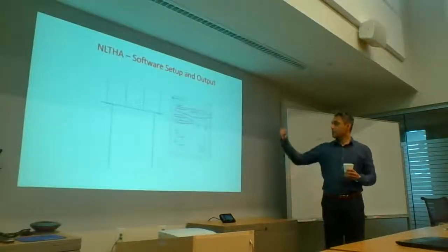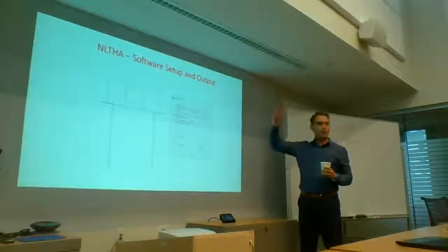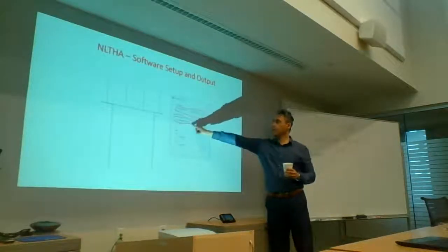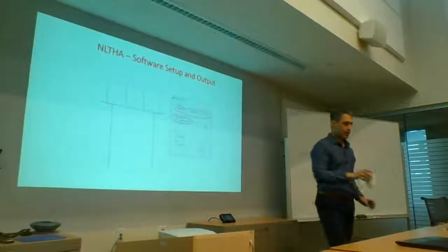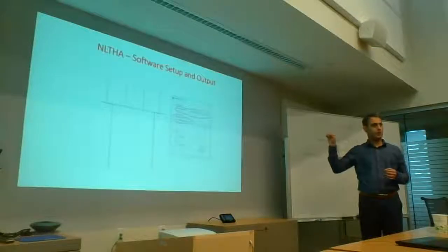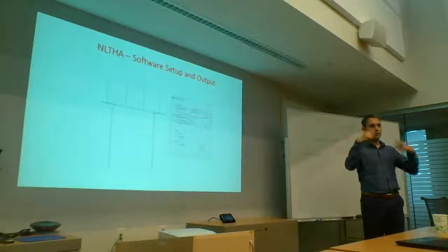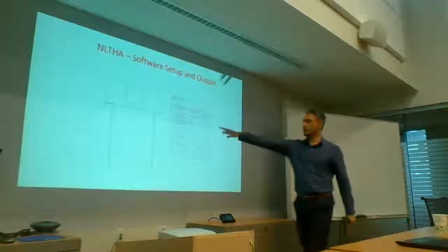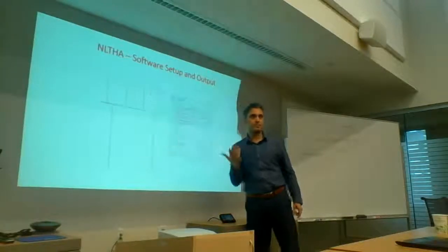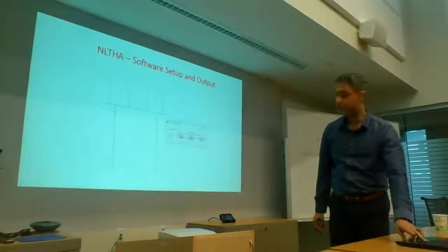And then I say, okay, I'm going to look at my deformed shape. Show me my deformed shape for this time history, but show me an envelope. So you can imagine that this is going to look funny. Every node that's going to show up on this graph is at its maximum displacement, which is not going to be concurrent. So this node might be getting to its maximum at some point, and this node is not going to be at its maximum at the same point. So sometimes people look at this and go, what is going on here? Okay.